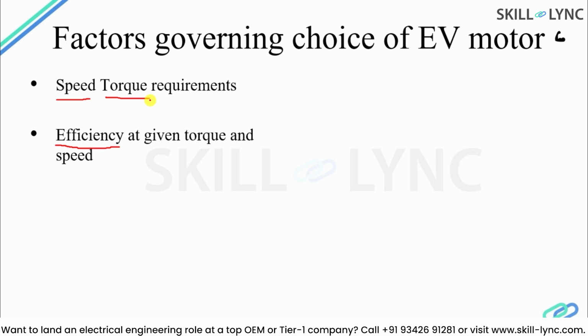Let's say the motor has 80% efficiency and all other stages are also around 80% efficiency. Then the overall efficiency will be less than 50%, because there are 4 to 5 different stages connected back to back, so with the cascaded efficiency of all stages, the overall efficiency of the vehicle will be very low.